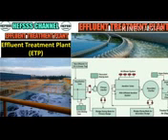BOD is the measure of the amount of oxygen required for bacteria to degrade the organic compounds present in the wastewater. So the most popular parameters in wastewater analysis are BOD, COD, TOD, and TOC. TOC means total organic carbon, and TOD means total oxygen demand. So these are the entire operations of the effluent treatment plant and process.